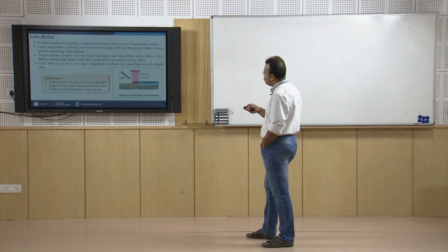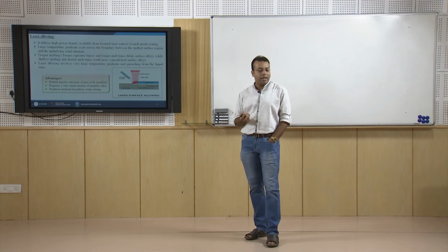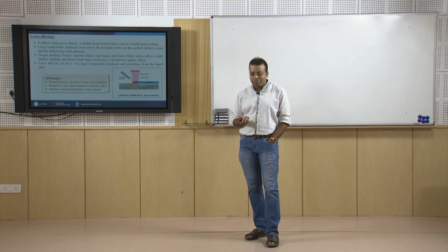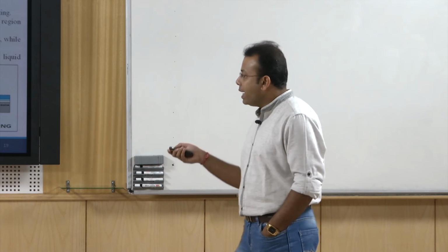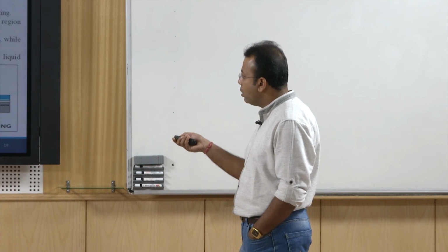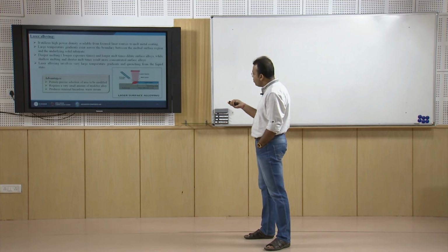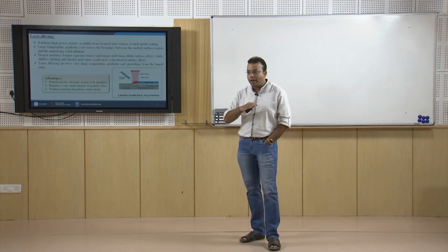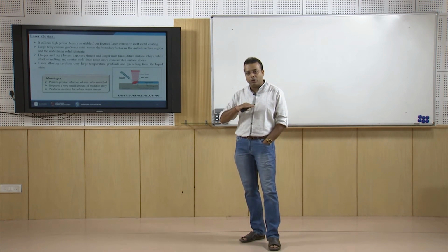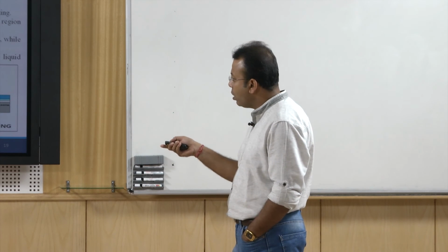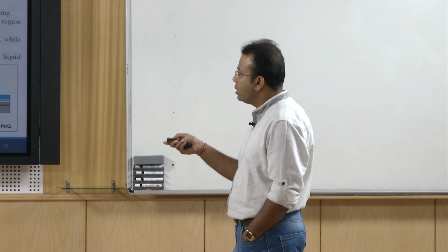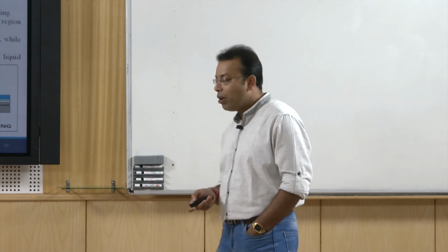From another side, we use some kind of powder, either a coated powder or an anti-corrosive, anti-rusting powder. By heating that powder with the laser beam, it makes a layer onto the metal surface, or base metal, so you are making a coating on top of your substrate. That is why it is called laser alloying.